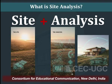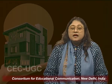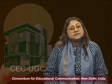So we can say that site analysis is the systematic study of the existing environment and its influence on architectural design and layout. In residential design, site analysis will help you decide the orientation of the rooms, and control the heat, glare and ventilation aspects. It will help you respond to neighborhood character and improve environmental comfort without much mechanical dependency. So you might be thinking, what is to be done in site analysis?